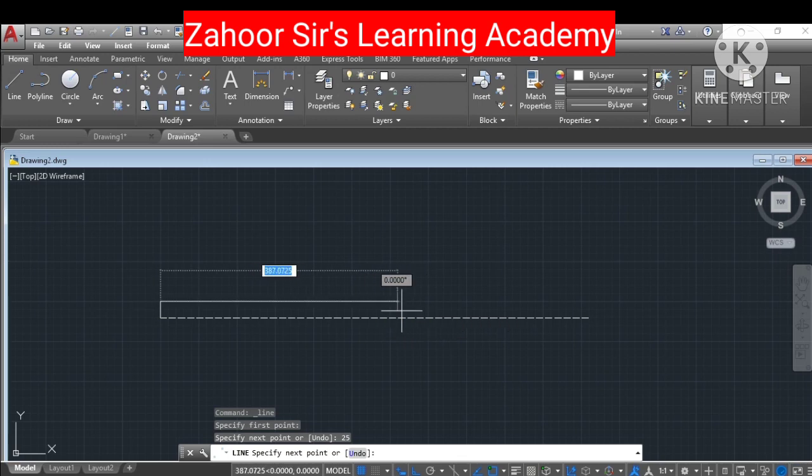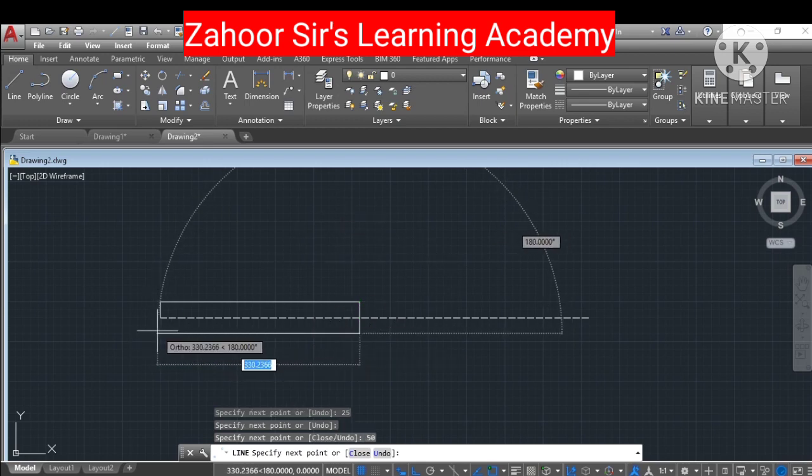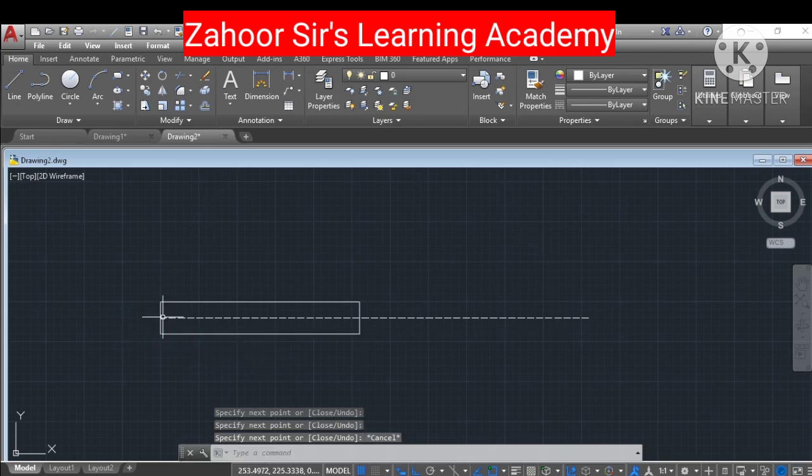Then I go to this side, let's say this much to this end. I'll press the left key and then go down 50 mm, so that is the diameter of the shaft. Then I'll connect this with this, then escape. So this is how I have drawn the shaft.